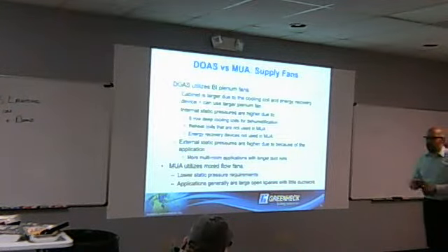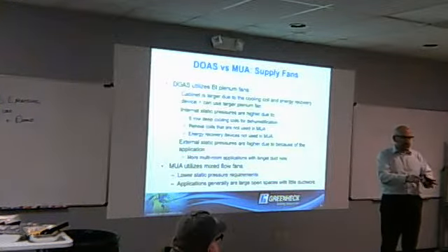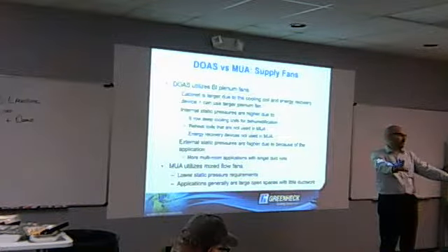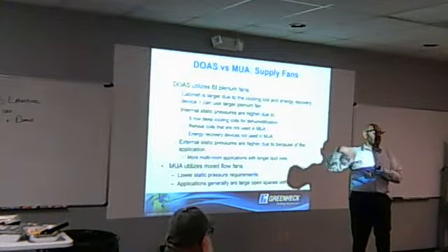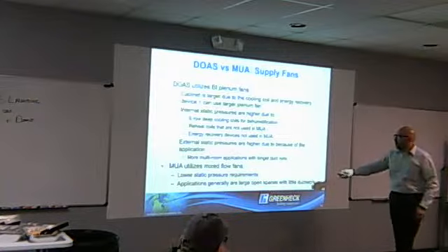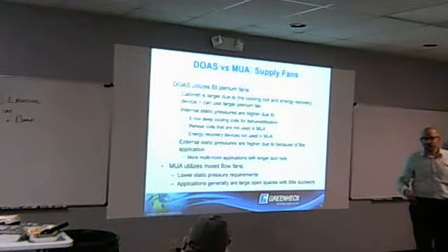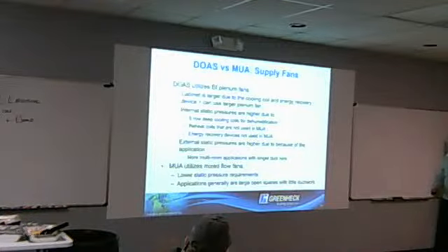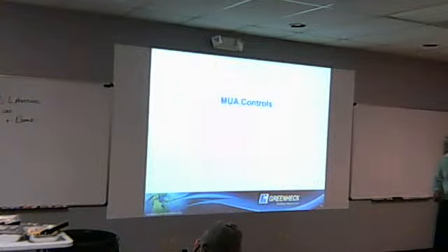Ducting: remember, I talked about that 3-way discharge on the makeup air for your warehouse, it just comes in, short duct runs, just putting air in the building. When you get to the DOAS unit, you're talking about ducting to each room. So now you have more static. There's a reference here to multi-room application with longer duct runs. We need to accommodate for that static, so many times the engineers are reporting that. And then the mixed flow wheels and large open spaces with limited duct.